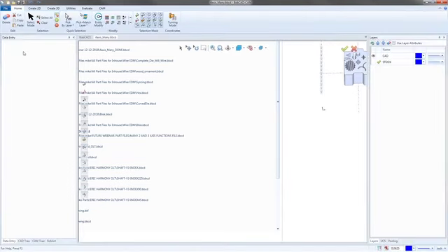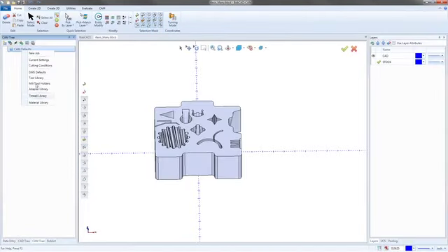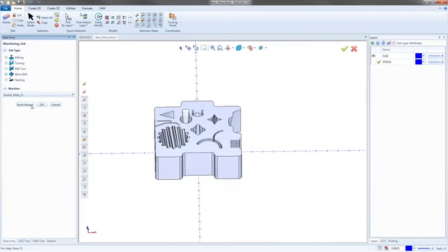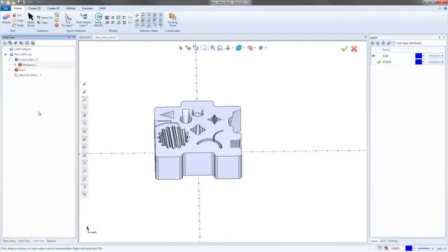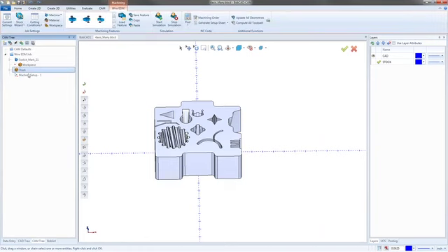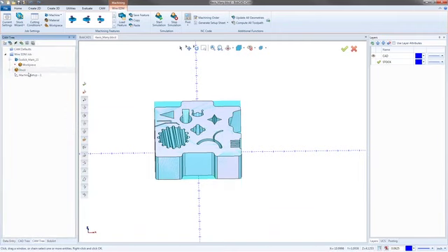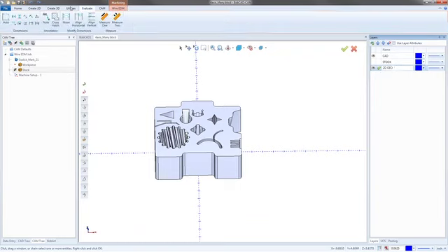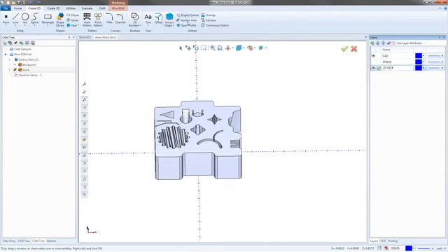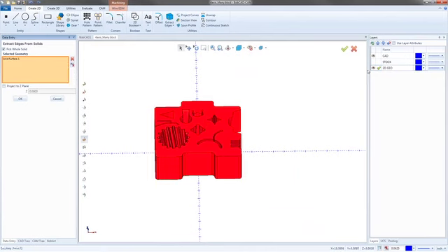All right, we'll open this up. Let me make my stock real quick. New job, Wire EDM, stock wizard. Next. Whoops, didn't even mean to do that. Stock wizard, rectangular. I'm just going to hit OK. The origin's down at the bottom, I'm not really too worried about it. So blank that out. All right, so right here, add new layer, 2D Geo. And we'll re-pull this geometry. So utilities, extract edges. I'll create 2D, extract edges from solid, pick the solid, OK it.